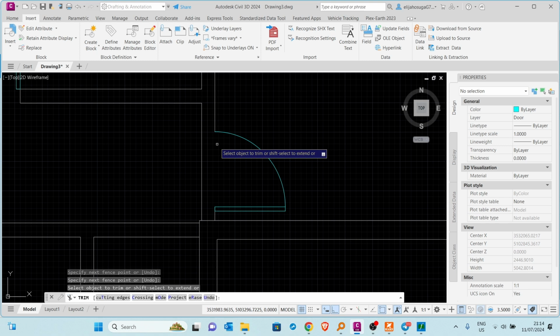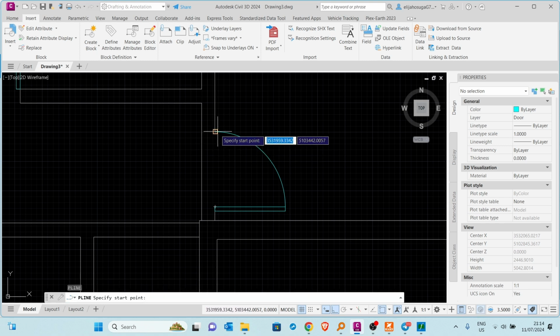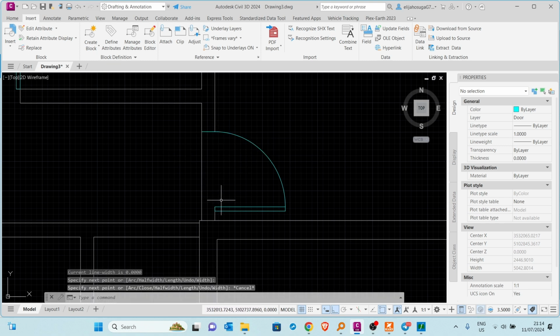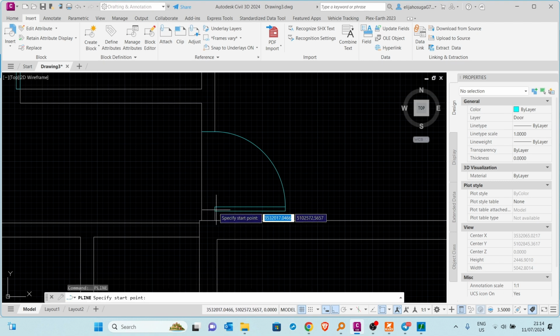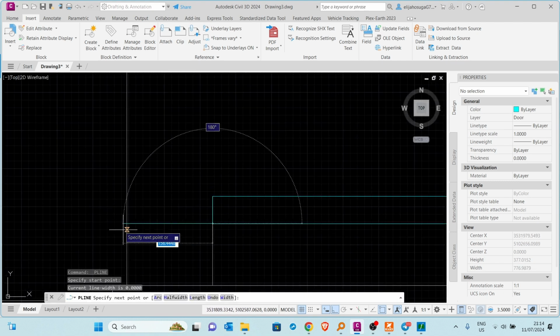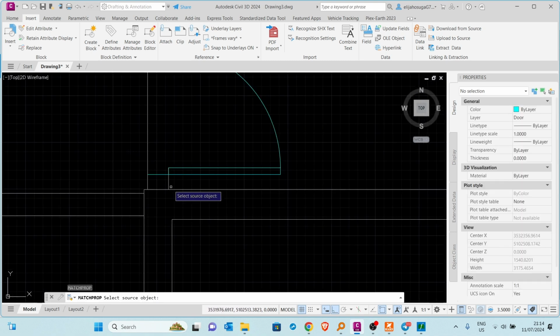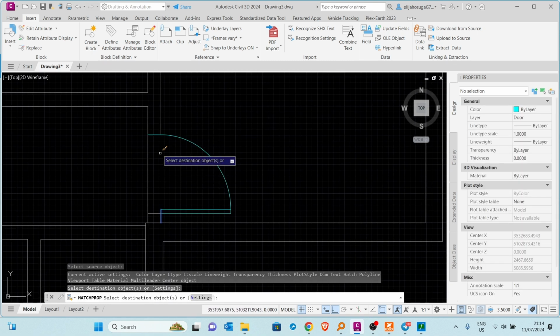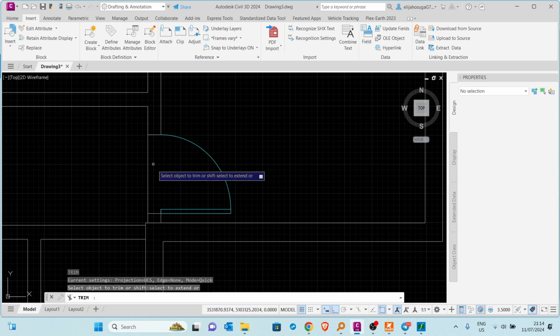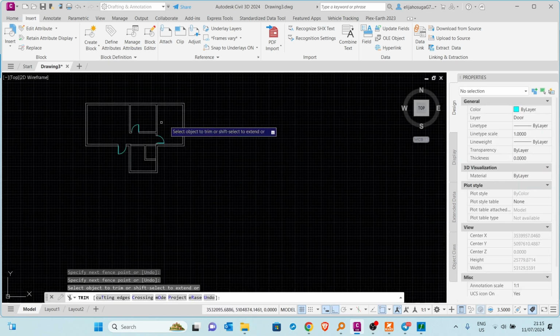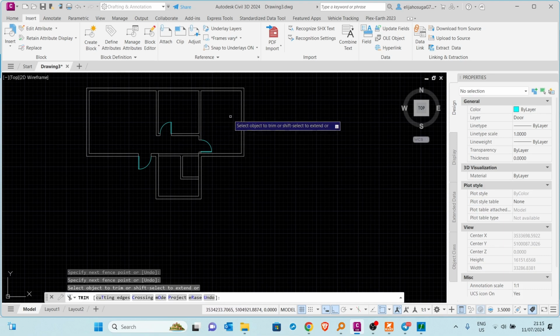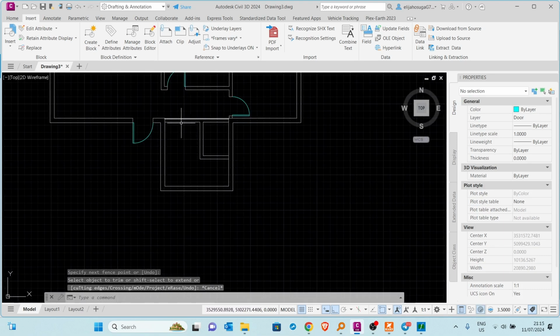You trim that part. And then you create a polyline from that point. You create another one by just hitting the spacebar. Then you match props, these walls and this wall. And then you trim off your entry to the first bedroom and to your second. Very well. Now we need to do another door for this toilet.